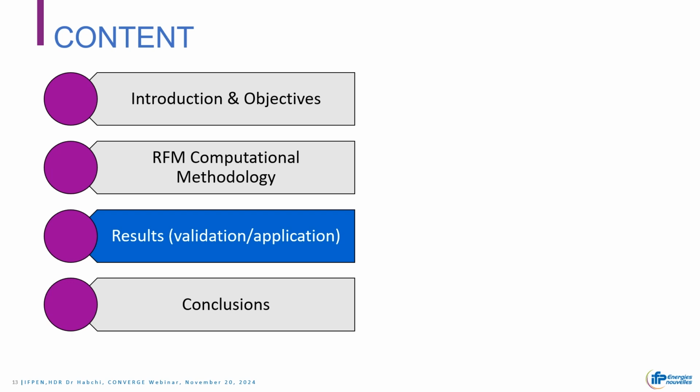It's well known that for cavitation, for example, the dissolved gas will make the cavitation easier to happen. And nucleation in general is promoted by dissolved gas. So the capability of this thermodynamics method to track the interface and the two-phase regions is really the most important feature of such modeling.